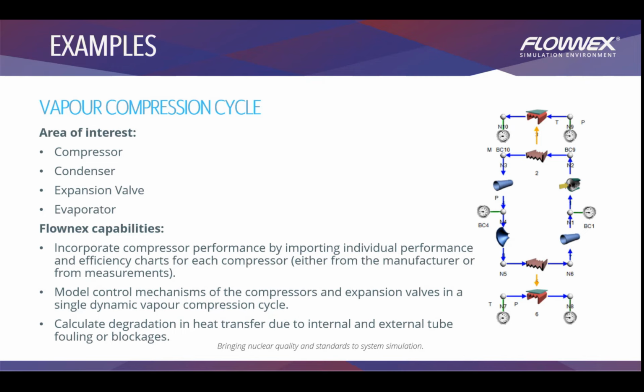Then you can also do calculations of heat transfer due to internal or external tube fouling. This is just an example to explain that you can also do heat transfer in water distribution systems, to make sure that the water you're distributing is not losing heat or gaining heat, because sometimes we'll be distributing water over long pipelines. And then we have to make sure that the moment the water reaches the end point, it's not too hot or too cold due to weather conditions.